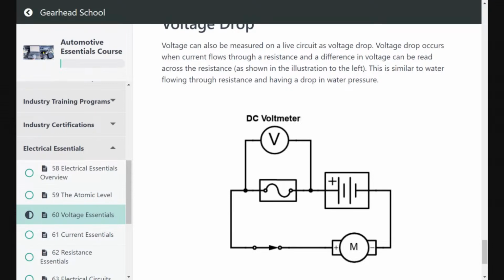So you can use voltage drop. It is absolutely the way to find unwanted resistance. An ohmmeter is, well, close to useless to do this. People always ask me, what would you get rid of if you had to get rid of something? I just don't fix cars with an ohmmeter, and I'm sure somebody's going to disagree with that. But you'll find specs on some component, and it'll have a resistance spec, and you'll measure it in specs, but things still don't work. And if you want to find resistance where it's not supposed to be, do the voltage drop principle. It's a good test to run.